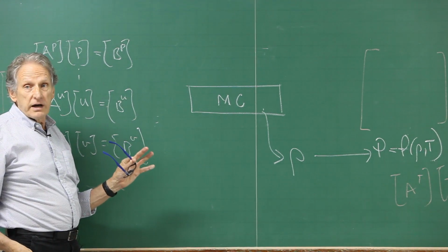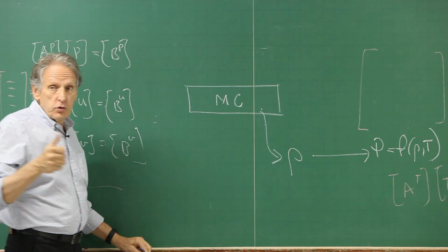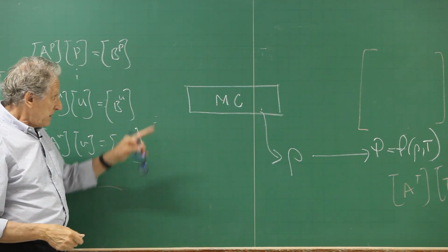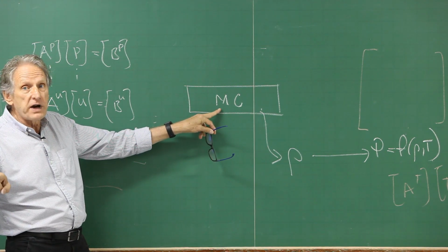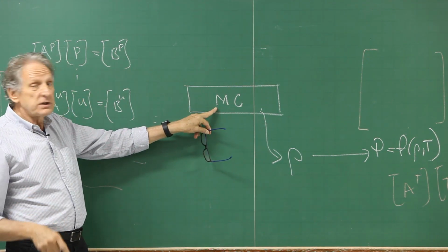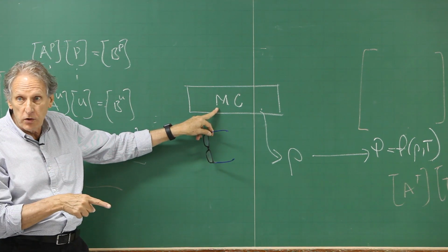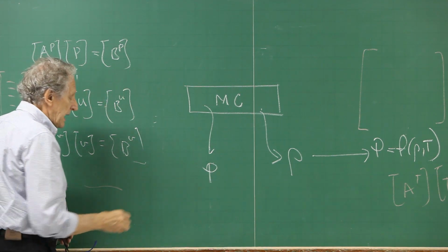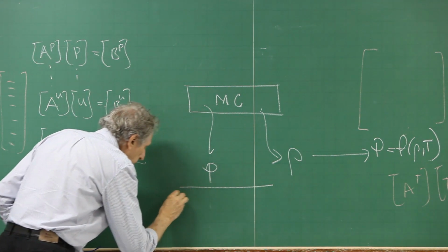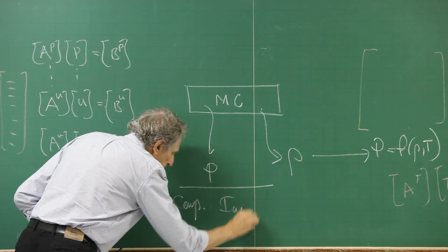But what we can do here also, from mass conservation, and to use an algorithm, in the mass conservation you substitute U as a function of pressure, and density, which appears here, as a function of pressure again, compressible flow. And then you can extract pressure here. And this can be for compressible and incompressible.